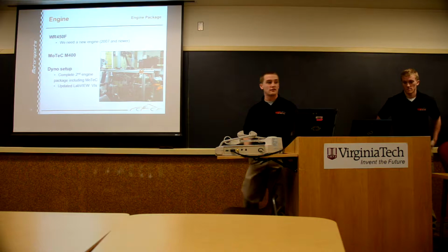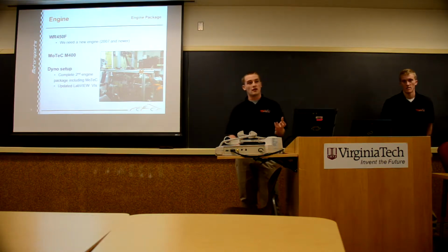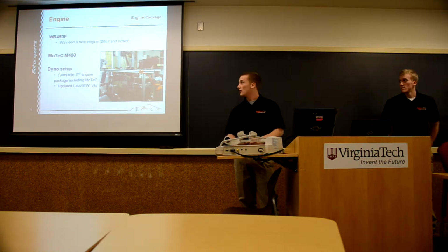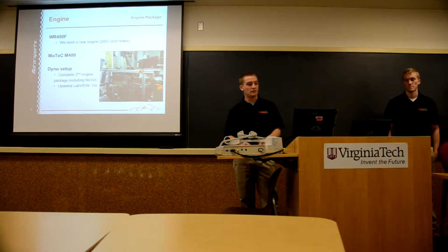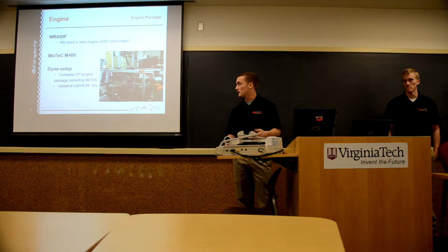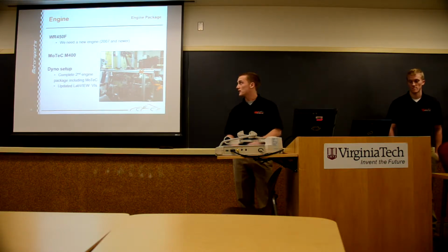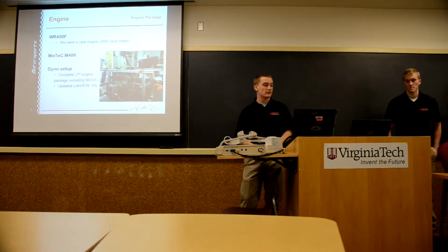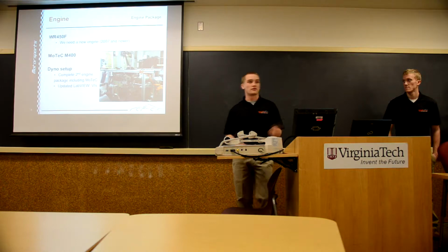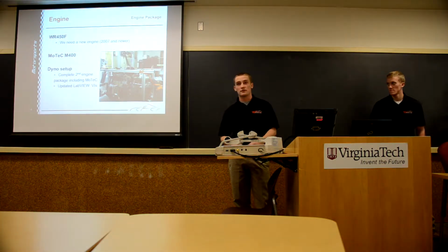I believe it's imperative that we update the engine, something 2007 and newer from the WR series. 2007 is the year Yamaha implemented a myriad of changes and upgrades to the WR series. It includes a new balancer, a new case, head, a piston cooling jet, and it integrates an oil tank. In 2012, they also added stock fuel injection. So if we're fortunate enough to come across a 2012 or newer engine, we'll certainly accommodate for that.